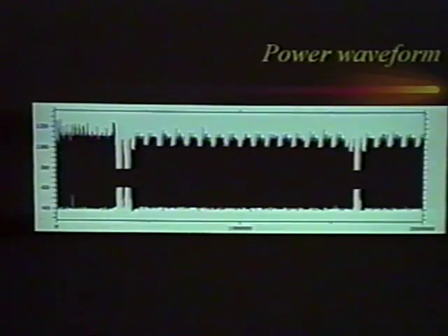What is important to realize here is that this is not purely a smart card attack. We could do the same attack on any CPU. It could be a CPU in your PC or in any box in the network, as long as we can measure the power consumption or the emission of power. The problem, however, is that this smart card runs on 3.5 megahertz, while your PC runs on 1 gigahertz, which is quite a bit faster and quite a bit more difficult to measure. So we'll probably need a whole different class of equipment, which may be much more expensive.